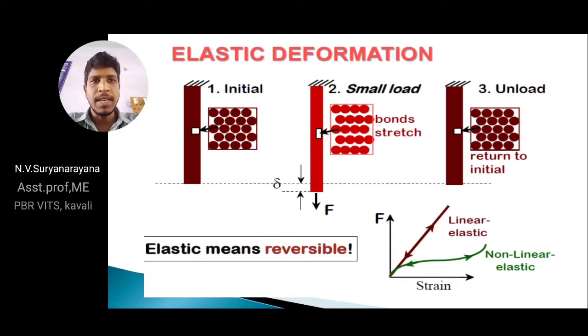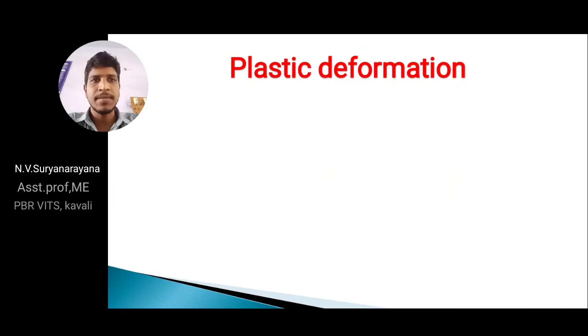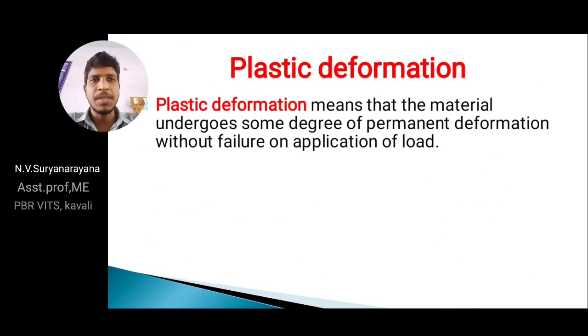Keenly observe the first figure and third figure; both are similar. Before applying load and after releasing the load, both are the same. Elastic means a reversible process. Next, coming to plastic deformation, it is not a reversible process; it is an irreversible process and a permanent deformation.